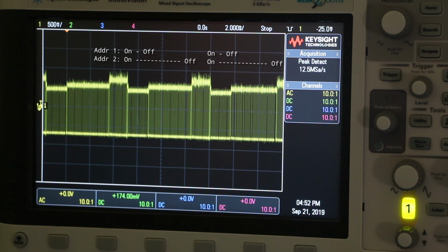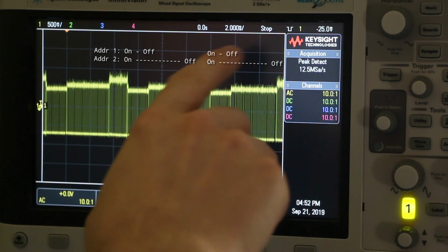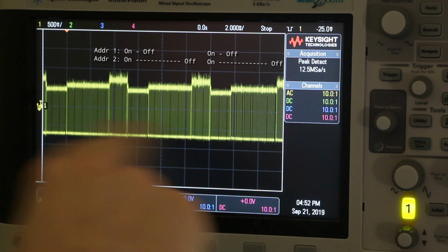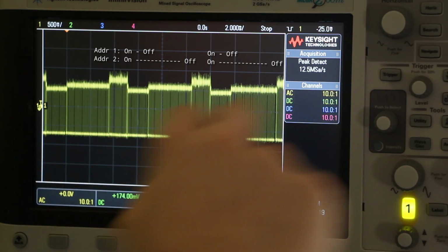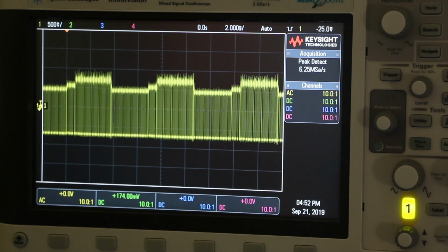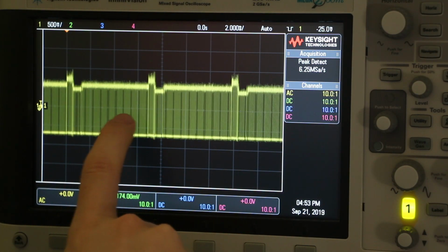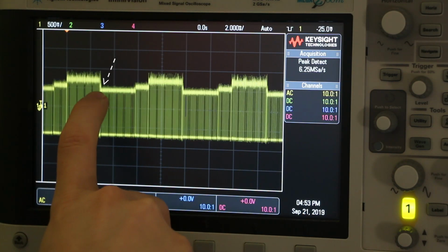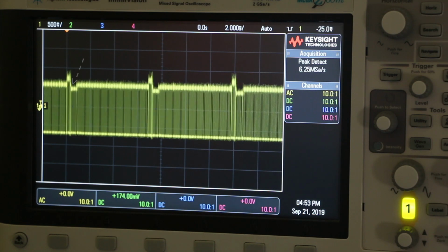Now, using that we can draw the waveform on top, and I'll try and do that after the video. And if we then press run again, we can start to see that the PWM is being controlled using this method. Now, as we've identified, the start of the cycle is actually the beginning of the low period, and we're not triggering off that very reliably.